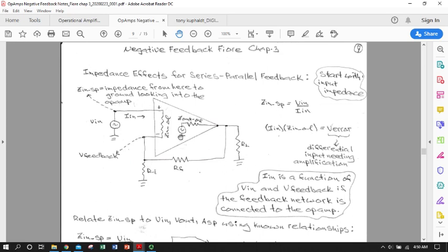If we look inside the op amp going out, we go from ground within the op amp. We have a voltage source, variable voltage source, and we have a very small usually output resistor, and now we're at Vout here, ready to go into our load. And then here's our feedback network. So we can do some algebra and relate some of these together using Ohm's law.